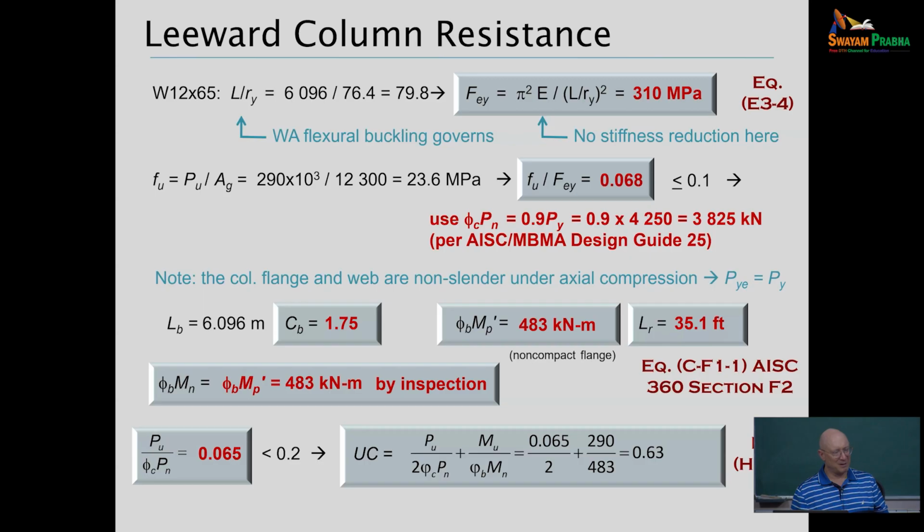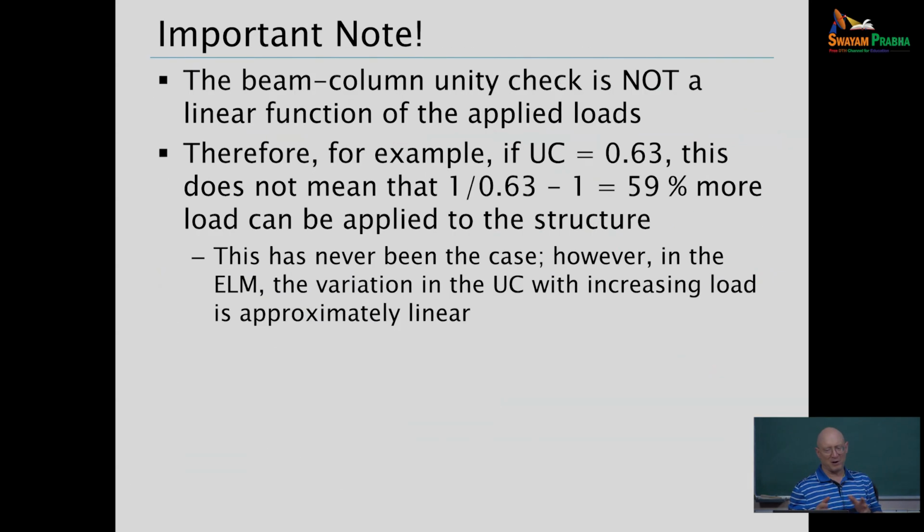Now, if we add just a little more load to this frame, we get even more lateral deflection, more amplification. So it's not like we can apply a large amount of additional load to this frame. So that's what this slide is saying. Some engineers might say, well, does this mean I could apply 59% more load to this frame? We're going to see that no, that's not going to work.